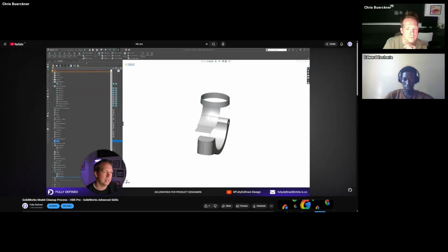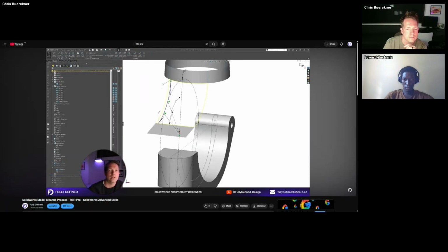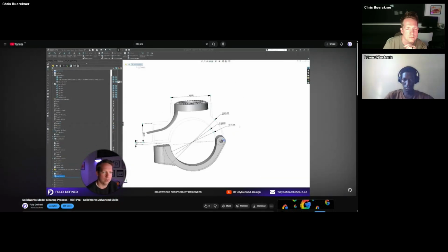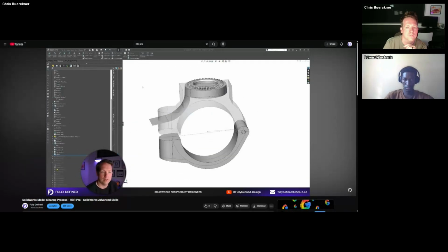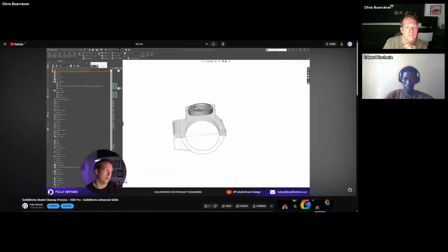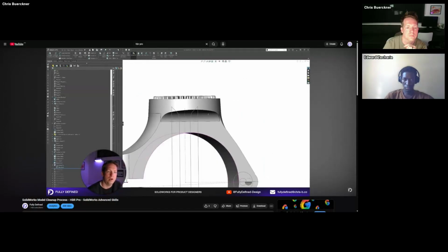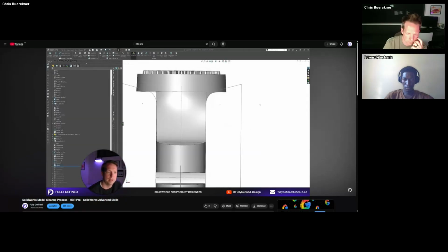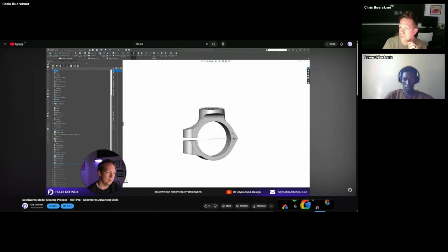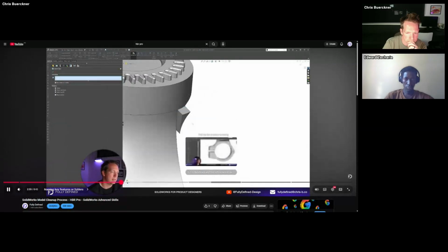The next element to group second to bottom in the tree are any draft features that aren't key to other geometry. This model is of a metal part with CNC finishing, so there aren't any draft features to move here. But in other examples, draft features and edge features are actually done in child parts, not here in the master file. So as I'm progressing through this process, I'm taking note of what the key elements of the design are and giving them names. As I do this, I create folders for these elements and start moving associated features into those folders. There doesn't need to be too many. This model has 10 folders.